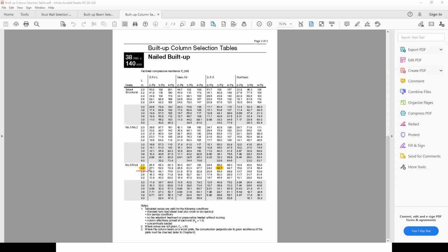Do you have less of a resistance? No, it's not that. The lintel here is because you're going to cut the stud, and they're going to be sitting on top. So in other words, this was the height of the wall, but the lintel is sitting on top, so the actual column height here is about 2.2. If you use 2.4, it doesn't matter, it's still good. But you can see that the height of the column is the height of the wall less the thickness of the lintel, and therefore you can go down to 2.2.